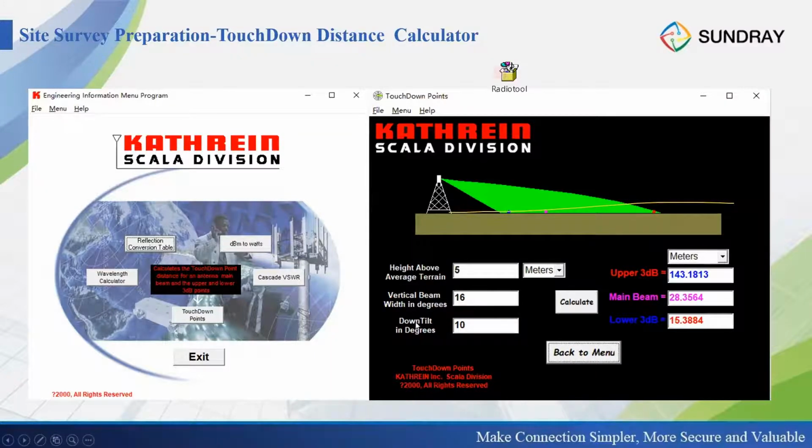Then there is the downtilt in degrees. When you put the AP, it is just a little bit tilted. Consider that the AP needs to look forward. It cannot look straight ahead, because the signal just goes far away and cannot provide coverage for the people on the ground. So the AP needs to look downward. But what's the angle? You can calculate the angle from this tool.